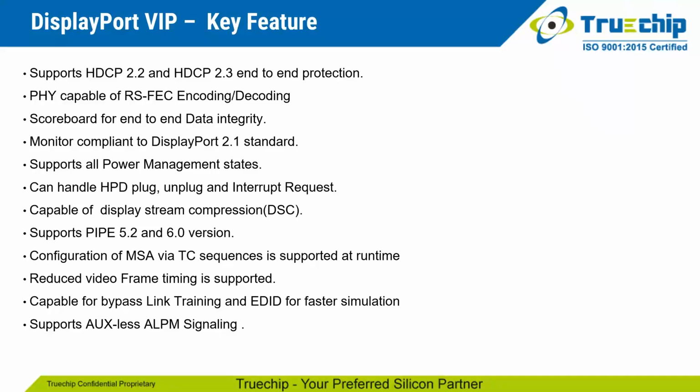DisplayPort VIP key features. Supports HDCP 2.2 and HDCP 2.3 end-to-end protection. Capable of RS FEC encoding and decoding. Scoreboard for end-to-end data integrity. Monitor compliant to the DisplayPort 2.1 standard. Supports all power management states. Can handle HPD plug, unplug, and interrupt requests.